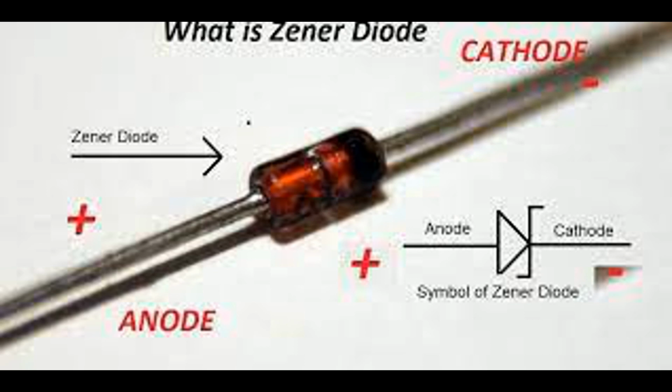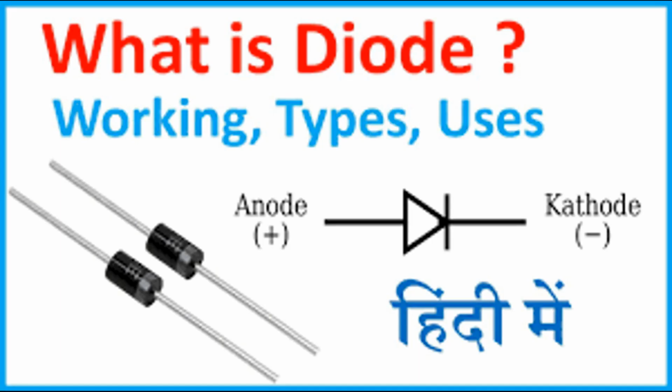When the voltage exceeds a certain threshold, the diode conducts and diverts the excess energy away from the protected circuit, preventing damage. Current limiting. In circuits where it's important to limit the current to protect components, diodes can be used in combination with resistors to create current limiting circuits. For example, using a diode in parallel with a resistor can limit current flow through a load.